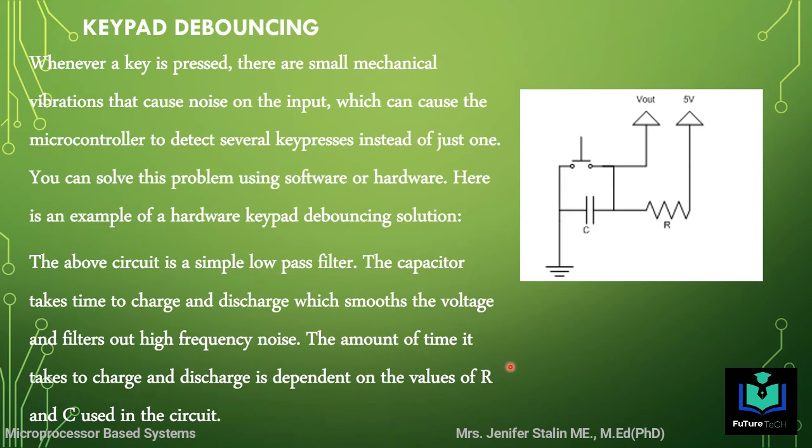When the key is continuously pressed after a stipulated time, the software analyzes that key 9 is pressed continuously, hence the user is pressing it, and it is not because of the mechanical vibration. So that thing should be taken into account.